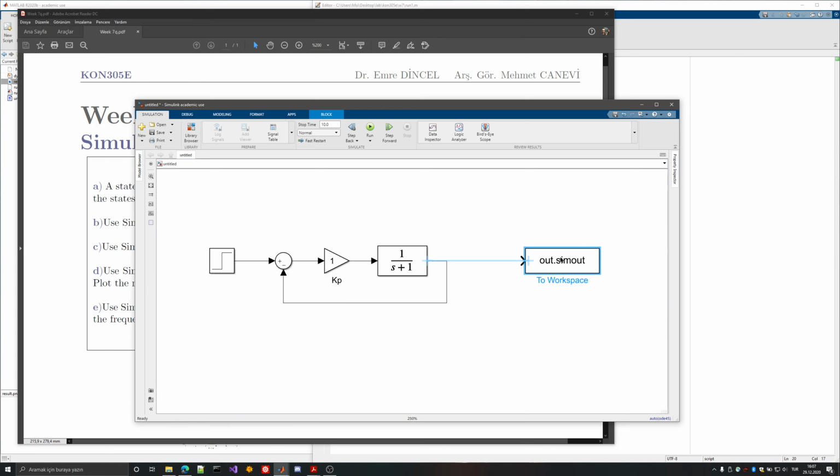output. Now, let's give some names here. This is the reference. Now, this is the output. So the controller, this one, generates U, which is the input of the system. So it generates the control input from the error. And this is the error. R minus Y gives E. E applied to Kp, or F(s), gives U, and U applied to the system will give